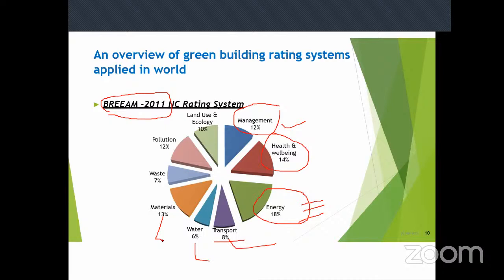Then you came to know, I think you know, fly ash bricks in place of burnt brick. Because the embodied energy of fly ash brick is 50% less than that of burnt brick. Even less is autoclaved aerated bricks, AAC bricks. C4X fly ash bricks and autoclaved aerated bricks, both are manufactured by C4X. They have a beautiful case study, they shared with me, thanks to them. AAC bricks have less cost and less energy consumption, 70% less embodied energy compared with clay bricks. So which material are you using?